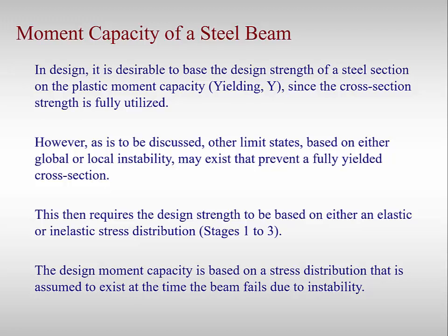Since the maximum moment capacity of a steel beam is defined by the plastic moment, it is highly desirable to have this as a design limit state. This means the cross-section will be fully utilized as it will be fully yielded. This is called the yielding limit state.